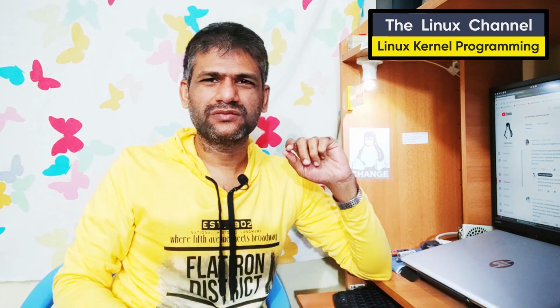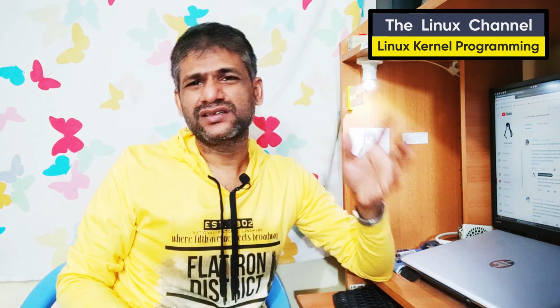In a case like GPIO, where you need to continuously set and reset something, like the state of an LED or of a GPIO pin, going with character drivers is a better idea, because you can do it continuously without any lag. And if you want to be more creative, you can even do something like PWM modulation. Of course it may not be truly real time, but you can somewhat make it possible. Some sort of a fan controller, which doesn't need accuracy.